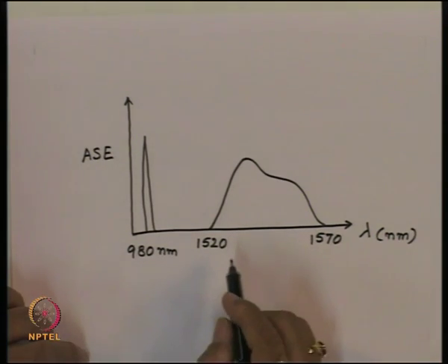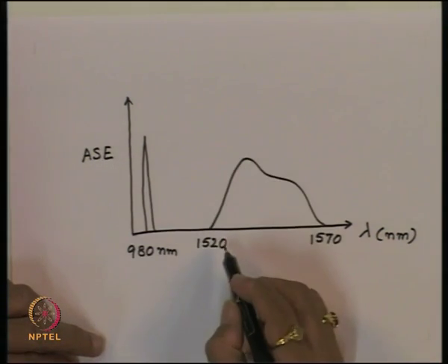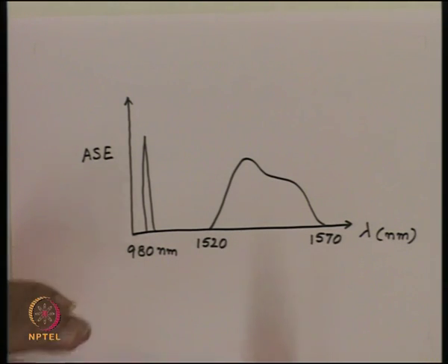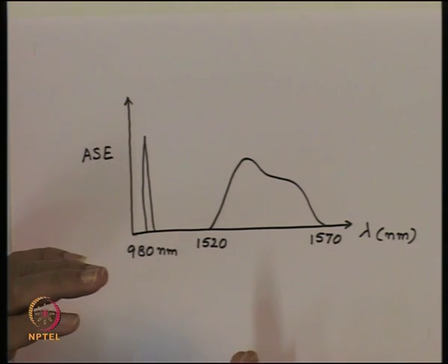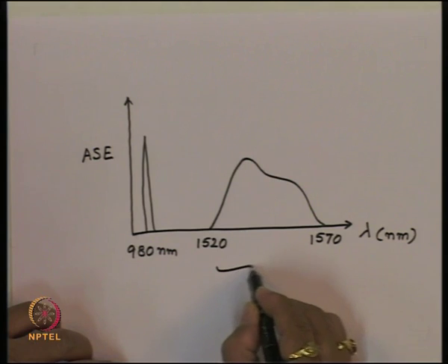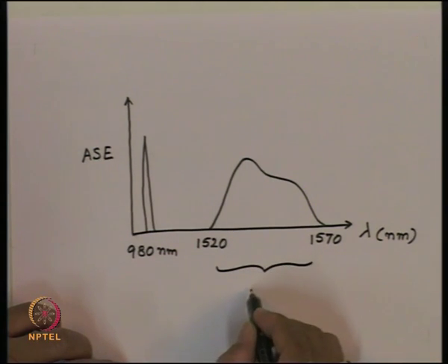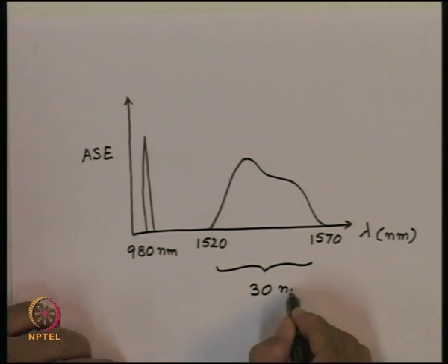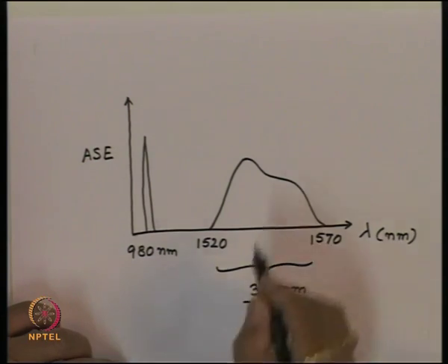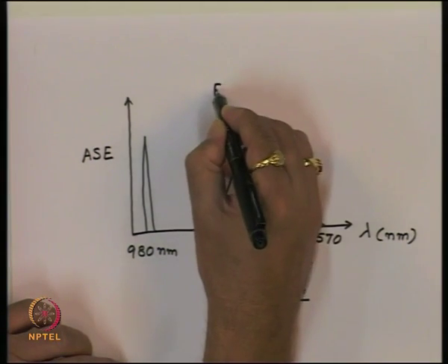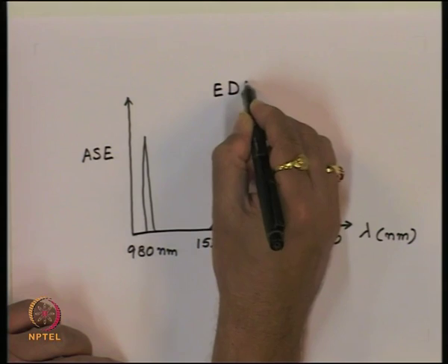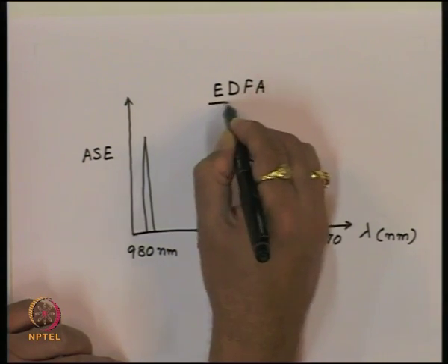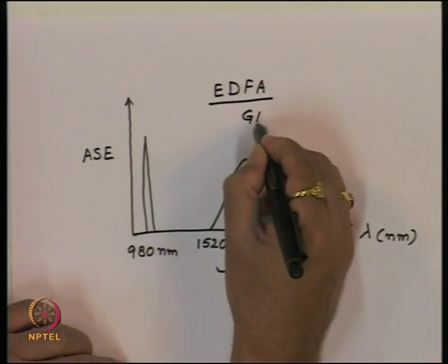What that means is that the EDFA essentially gives broadband amplification, typically over a band of about 30 nanometer effectively. So this is the EDFA gain.